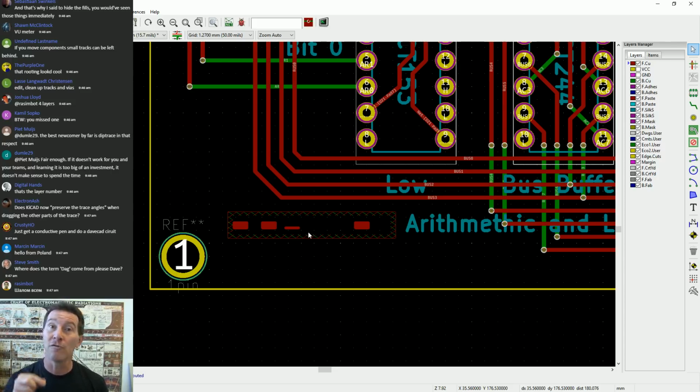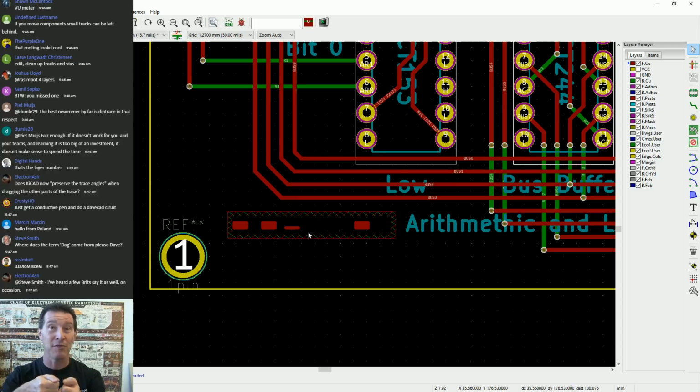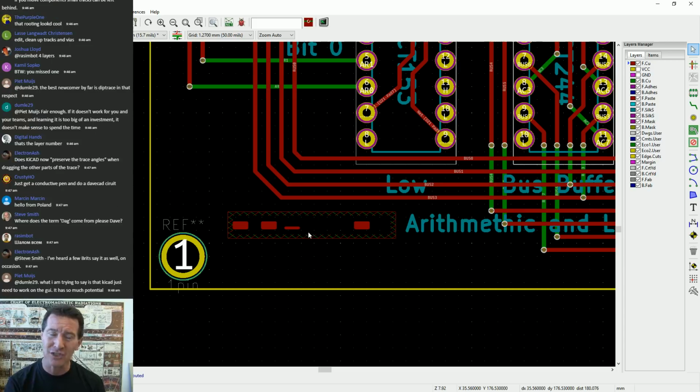Whether or not they've over etched or under etched, you can get in there with your micrometer and actually measure. If your 4 thou track is actually 4 thou, how much they're out by, have they over etched the thing, all that sort of stuff. So it's common to add a test coupon for this board. I don't care, right? We're not pushing the envelope here.